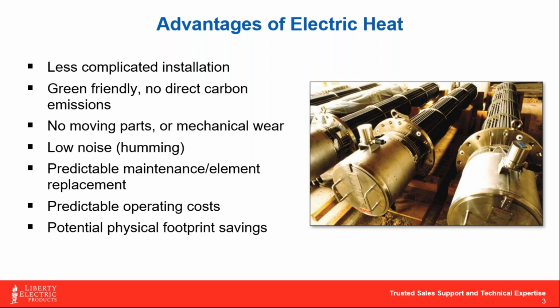The one thing I like as well is that you can test elements for their longevity, and depending on what the resistance readings are coming back, you can actually predict the rate of wear on these elements and proactively change them out before your process is disabled and you're down and losing money. So I think that's a very important feature.